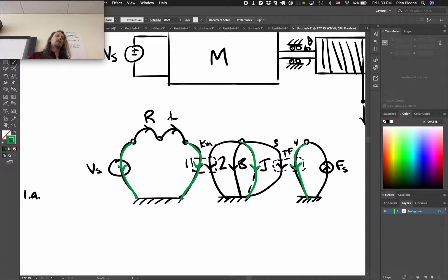At the end, we have to check that we've selected as few T-types as possible, which is L, our one T-type. So we don't want to select L into our normal tree. In fact, selecting the edge 1 here allows us to select R for D-type and not select L to reach this node.